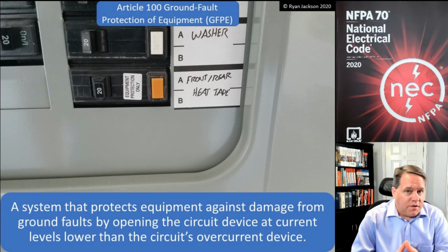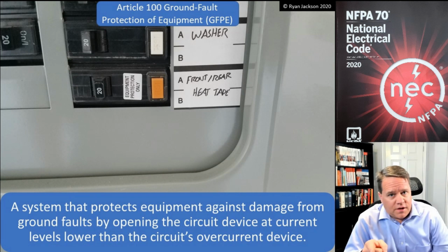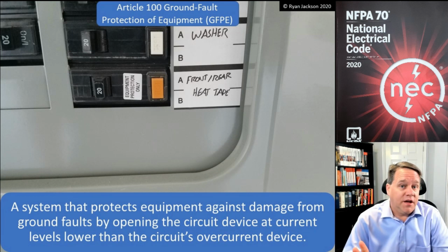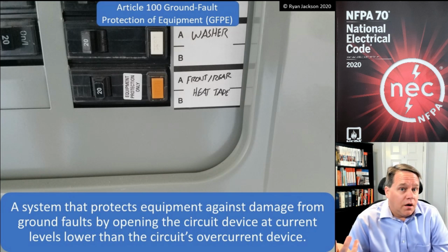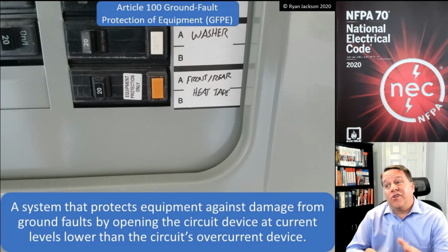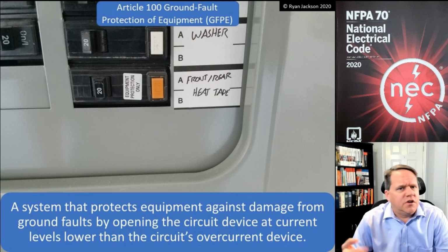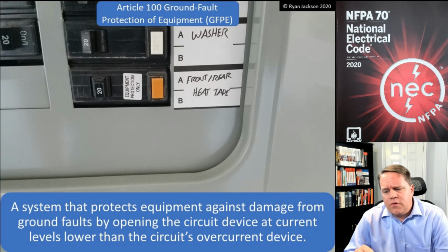Now, here's the big misconception when it comes to GFPE. What current level does that device trip at? Some of you might jump out and say 30 milliamps, and you might be right, but you might also be wrong. The fact of the matter is there's not a standard. A lot of manufacturers have kind of shaken hands and said, look, at the small, molded case circuit breaker level, we're going to just agree that we should trip at about 30 milliamps. But the product standard does not give a value.